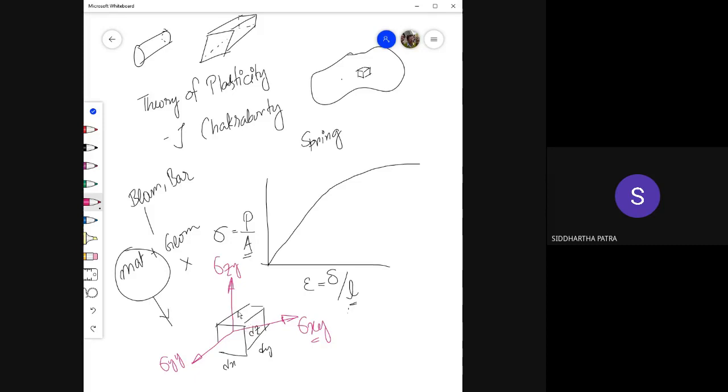And obviously on the opposite side you will have the same set of stress components but in the reverse direction. So only on the 3 planes you get 9 components. Actually, they are not 9 independent components. With laws of conservation of linear and angular momentum, it can be shown that the shear components are symmetric, which means sigma xy is sigma yx, and eventually we end up having 6 independent components.